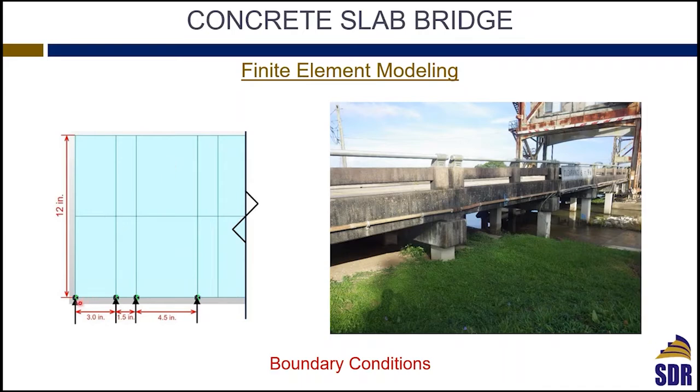If you want to try, do something similar and have only the slab supported at one node, or prevent the vertical displacement at one node only, versus having this restrained at multiple nodes, and look at the results. So we have to be very careful about the boundary conditions. Also, sometimes they have steel bars, which are called dowel bars, that are coming out of the pile bent or the bent cap, that are embedded into the slab, similar to what we do in approach slabs. That also will contribute to preventing the rotation if you have the bar or if you don't have the bar. So the boundary condition is critical to be taken care of.